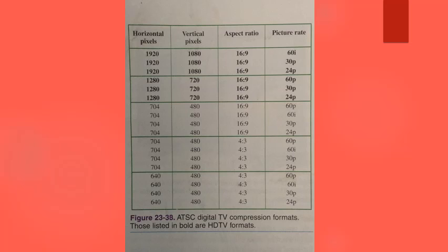You may have an HDTV receiver connected to a display unit that cannot produce the higher display quality, thus defeating the purpose of HDTV. Some systems simply take the existing NTSC system and double the number of scanning lines, but this does not provide any new image information. This is like using a photocopier to double the size of an original image. Since no new image information has been added, picture quality cannot be enhanced.